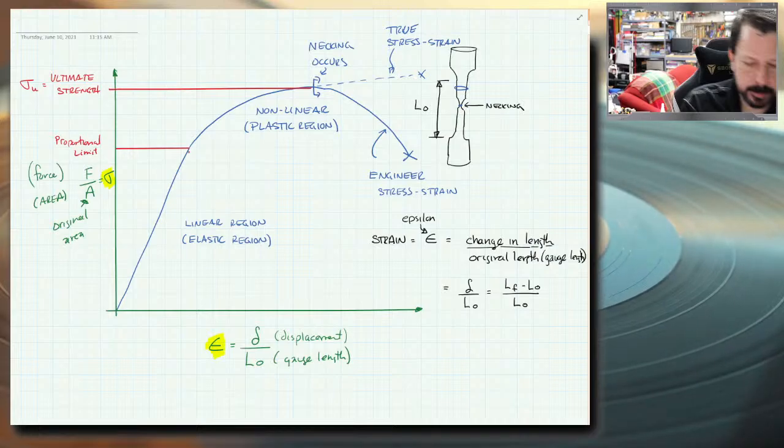So what we do instead is we say, I'm okay with some amount of strain in my design, but it's a really tiny amount of strain. So I'm going to take 0.2% strain, and I'm going to say that I'm okay if my design has 0.2% strain, change in size of objects.